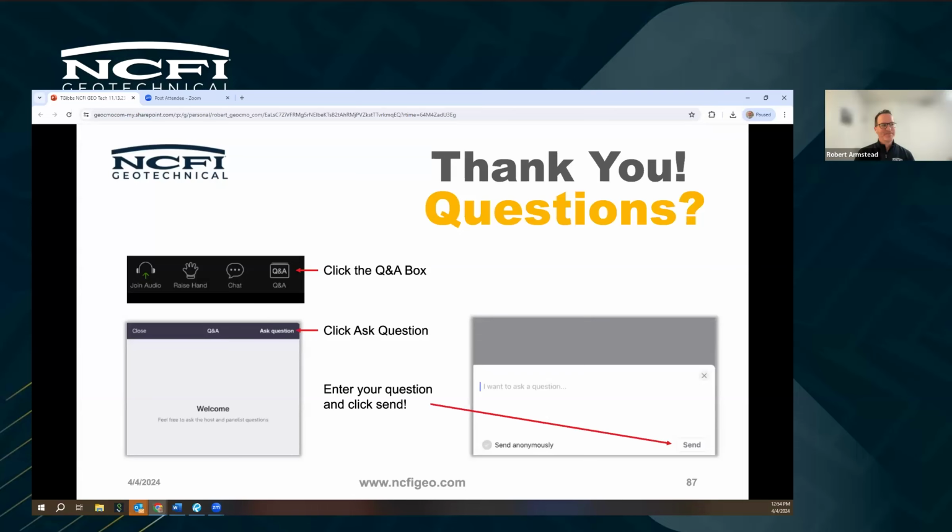So that is one of the challenges. The testing that we publish is based on free-rise samples. We have done some testing on constrained samples, but basically they're just constrained in a mold. So we'll take a 4-pound foam and put 5 pounds into a 1 cubic foot mold and then test that material. That doesn't really tell us anything about the soils per se.